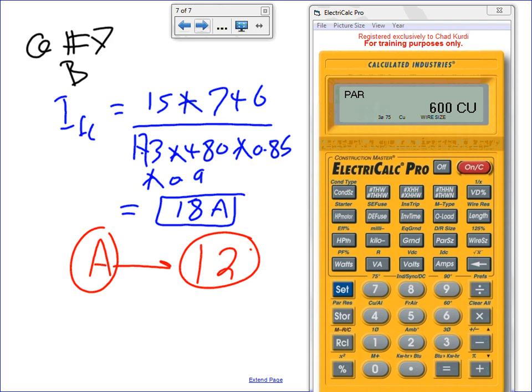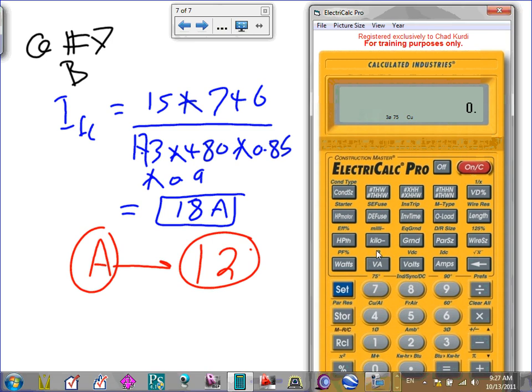Okay, let's do this. We can do this in the calculator. That's easy. Let's do this in the calculator, guys. Okay, here you go. How many horsepower? We're going to do it together. Am I set to 3-phase? Yes. Set up 3-phase. Let's put the horsepower, 15. Here's my 15 horsepower theoretical value. And then I need my voltage. My voltage is 480. And you hit the voltage here.